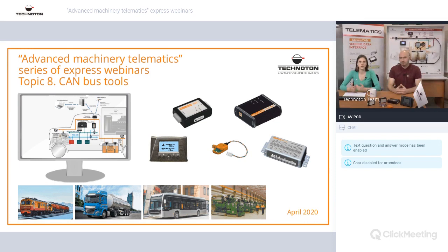You need to read data simultaneously from both buses, and your GPS tracker is able to get data only via CAN. So there is no J1708 input, just one CAN input. That's why you need a converter to get data from both types of buses. Or sometimes GPS trackers are limited in how many millions of messages they can take from the CAN bus, and they need already filtered and processed parameters to read a specific group of those parameters.